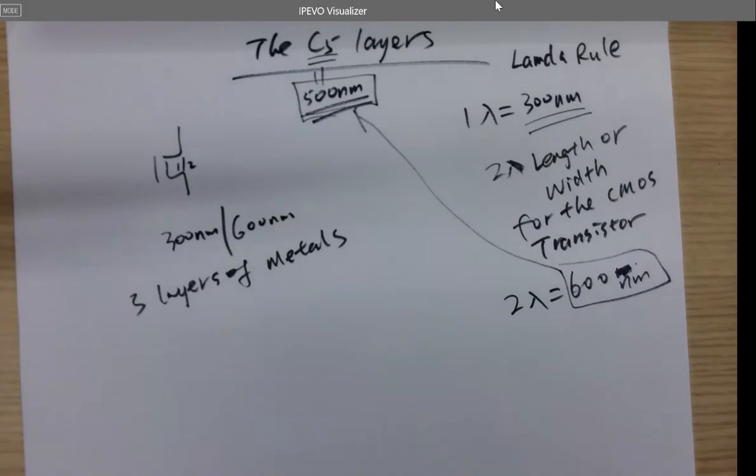So we sometimes still worry about the routing. But if you have like 4, 10 layers, you just put them next to each other. It's going to be fine. So all the vias and traces are running in the intermediate layers instead of on the top or bottom in the visible layers. So the computer's motherboard, if you open it up, or your smartphone's motherboard, the PCB, you can see the components are really close to each other. There are probably more than 10 layers in it. So C5 provides 3 metal layers.